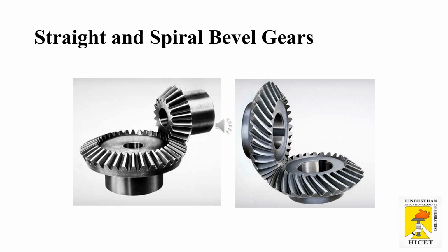Straight bevel gears can operate under high speeds and high loads. These gears are noisier in operation at higher pitch line velocities. These bevel gears can be found in automobile differentials, blenders and conveyors.